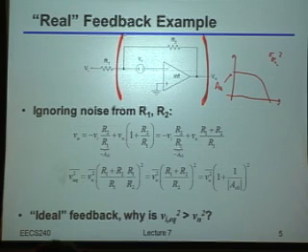What kind of input signal, what's the units of the input signal you typically think of feeding into this kind of amplifier in this particular configuration? Yeah, you typically feed a current into it, right? Because this is a transimpedance amplifier. So you're typically feeding a current into it. It has a resistive input impedance and creates a voltage at the output.